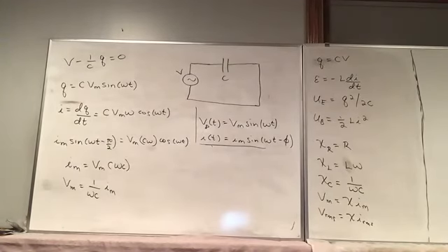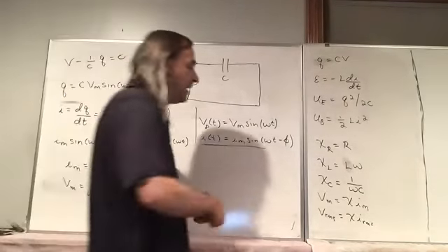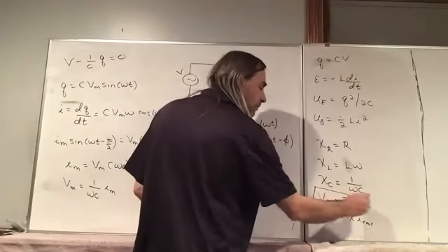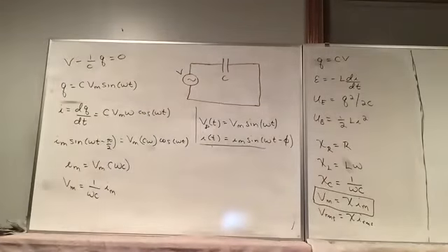So unless you have a purely resistive circuit, Ohm's law does not apply for alternating currents. But this basic idea works if you just look at the peak values or the RMS values, which is usually what we're interested in anyways.